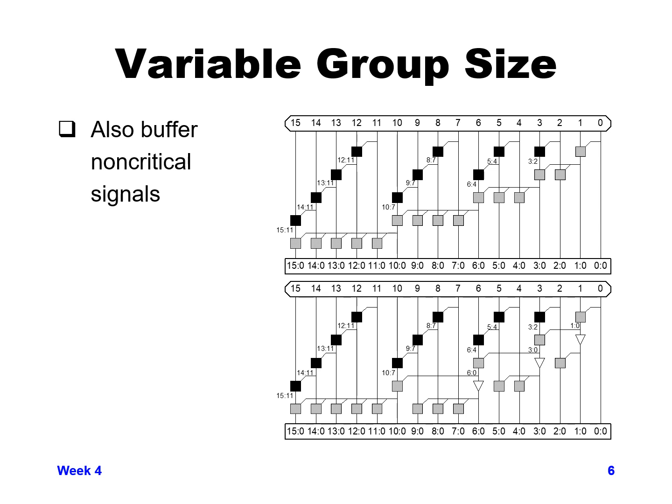So we can speed up that path to bit 6. Then we can do a similar thing from bit 6 to bit 10. We add a buffer in there that drives bits 7, 8, and 9, and so we get a faster delay from bit 6 to 10.